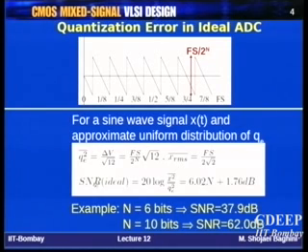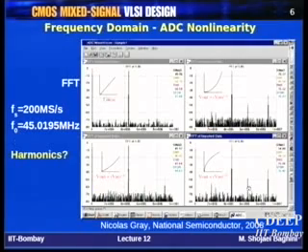There is a reason behind that. For example, you can use a sine wave with any amplitude or full-scale peak to peak, and then see whether this relation is valid or not. The noise floor you get at the output, and the SNR you calculate based on that, will it obey this relation or not? Before you check it, you will see this noise floor is not the same value you expect. Just to give you a hint,